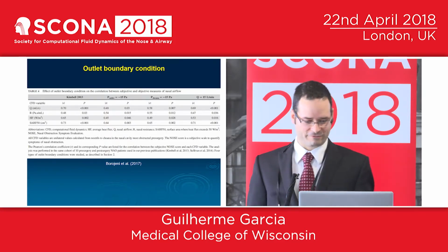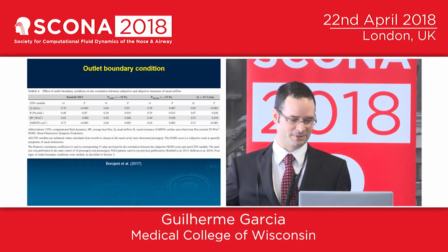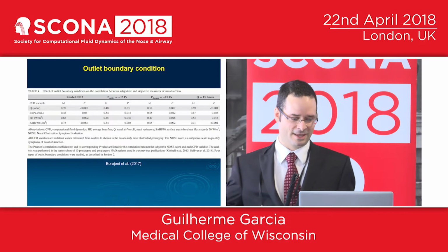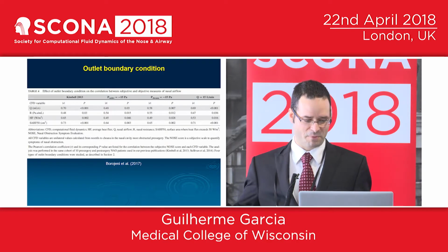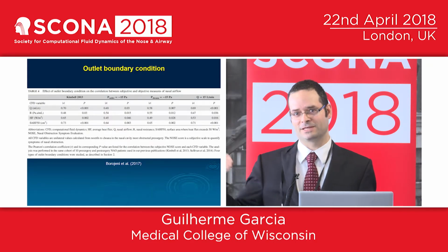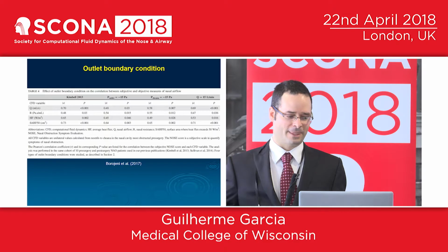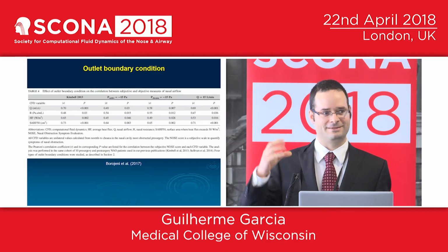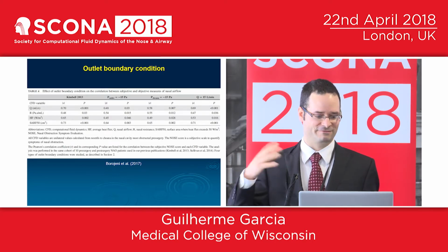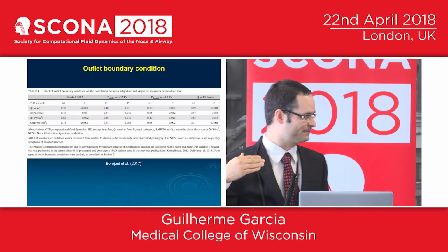Okay, so another topic that I think is often overlooked is the effect of the outlet boundary condition. Oftentimes in the literature, we see authors setting a constant pressure at the outlet, often like a 15 Pascal negative pressure as compared to atmospheric pressure. One thing to keep in mind with that is that the geometry of the nasopharynx is very flexible. The clinicians know this, but I think the engineers often don't know this.